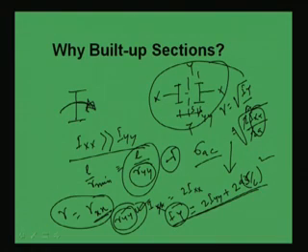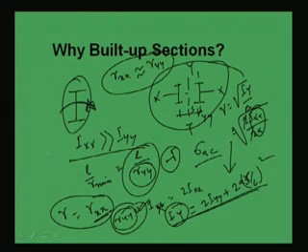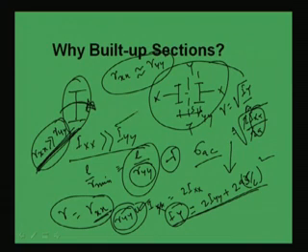So the built up member should be made in such a way that rxx will be almost nearer to ryy. Whereas in a single available section, rxx will be much greater than ryy, which is not desirable. So this type of section is not desirable for a compression member, though we are using it, but for small area, for small magnitude of load, this is okay. For heavy load we must go for a built up section.